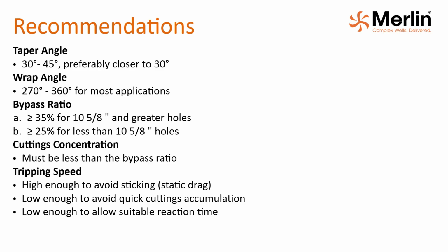Cuttings concentration must be less than the bypass ratio, but the actual maximum can be dependent on the following operation. Tripping speed should be high enough to avoid sticking or static drag, and low enough to avoid quick cuttings accumulation and allow a suitable reaction time.